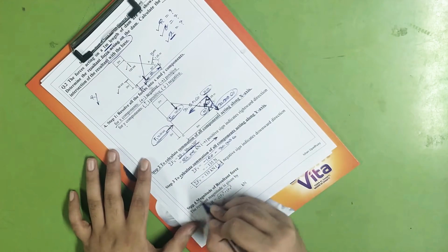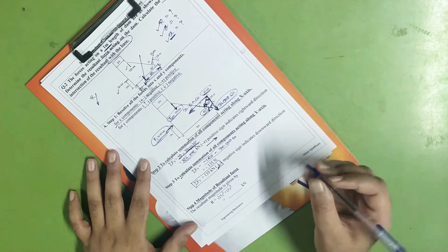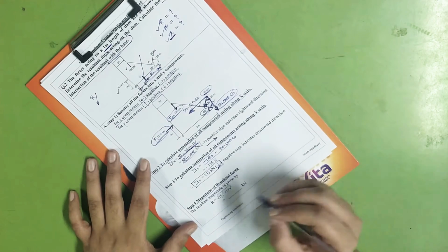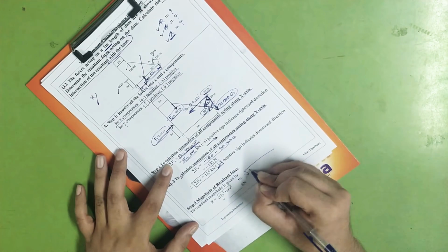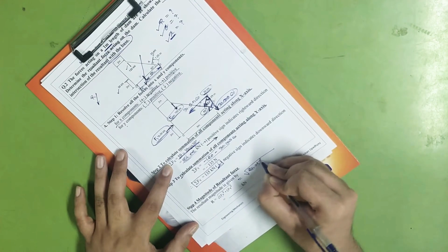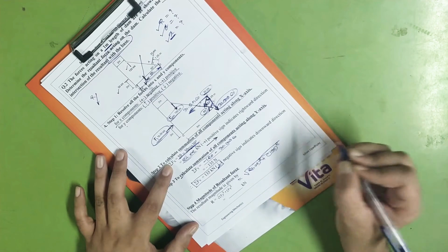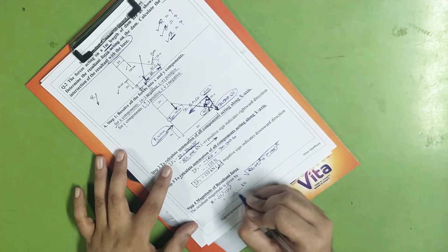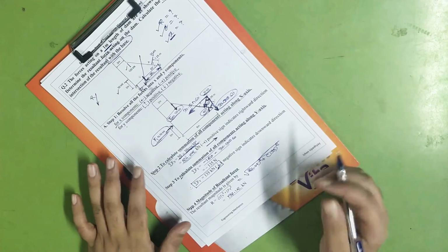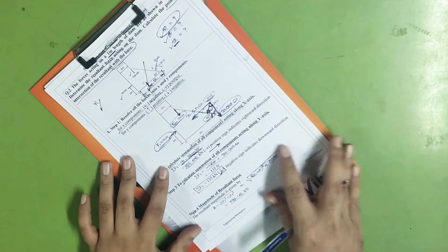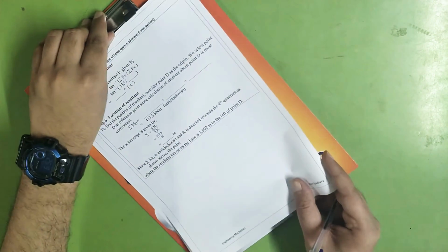Next we will go for the magnitude of the resultant force. So R is equal to the square root of summation of Fx squared plus summation of Fy squared. By solving this, I have to put the value of Fx, so I'll say the square root of 24.02 squared plus Fy is 135 squared. On solving this, I'll get the answer of R, that is the resultant, as 137.12 kilonewton. So I have got the magnitude of the resultant.